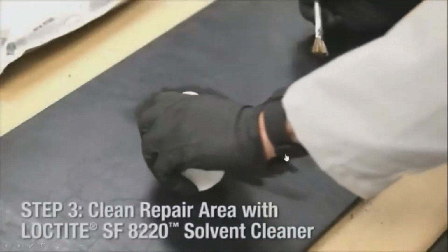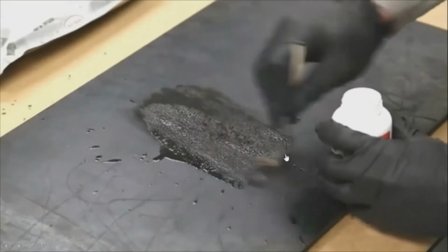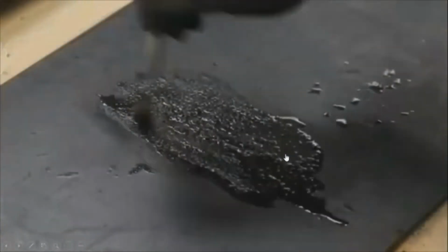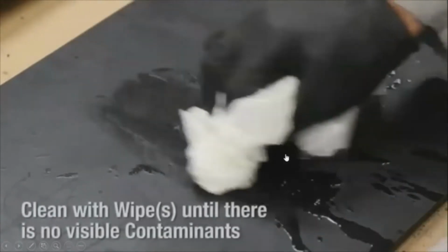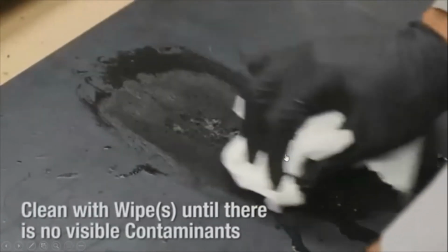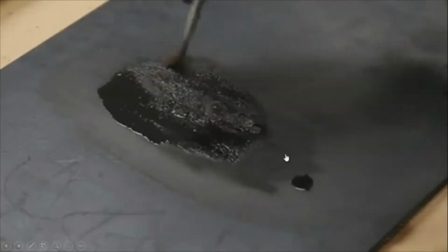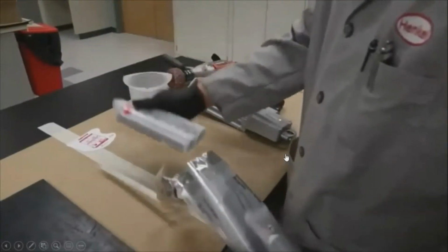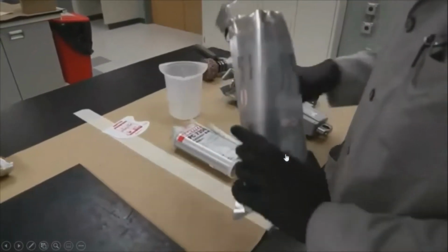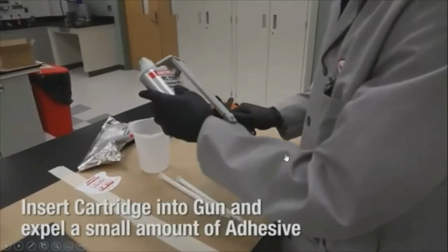Then we clean it manually, and you can use a solvent cleaner to do some minor cleaning. In this case we are using 8220, or you can use our more conventional product, SF7063, so that there is no loose material on top of the conveyor belt. Next we use an etching agent. The etching agent is a type of primer for the 7350 product. It increases the bonding between our product and the conveyor belt itself.